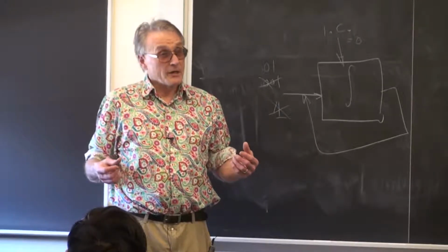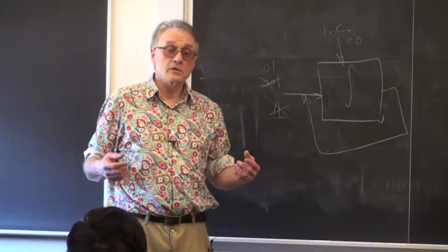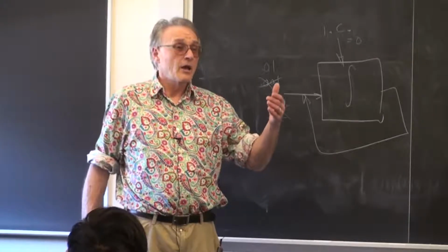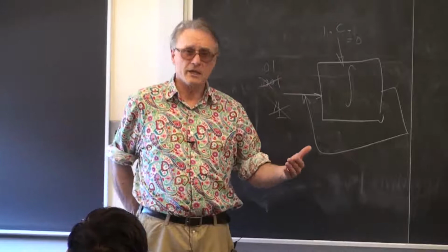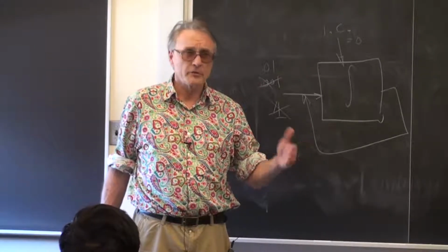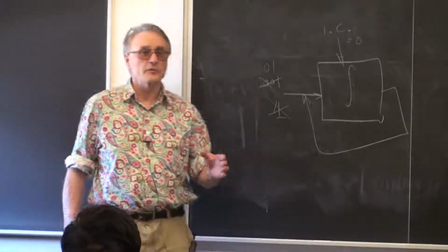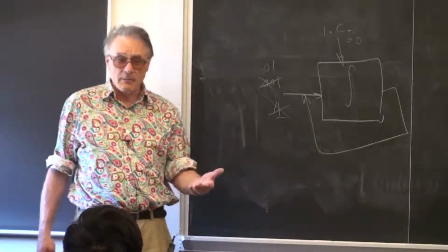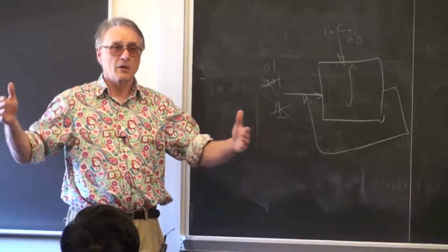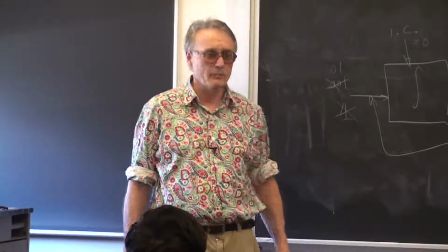And as it transpires, some forms of digital signal processing, infinite impulse response filters that have been factored into second order sections. Are you familiar with this idea of factoring into second order sections for stability? I'll do that later sometime. But if you have factored filters, they are very much more numerically stable, but it requires wide range of number capability, which is well done in floating point and poorly done in fixed point.